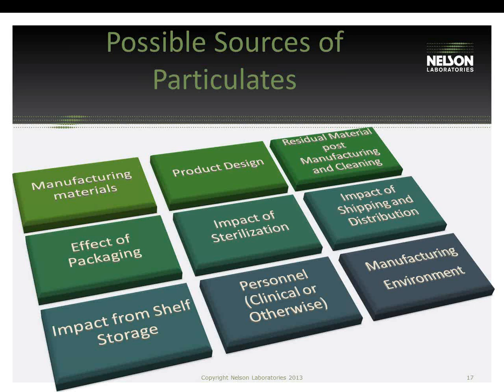Personnel, this is probably one of the largest ones, whether it be clinical or in a manufacturing environment or somewhere along the route from the manufacturing facility to the clinical facility. Personnel are probably the largest providers of particulate matter there is. We certainly find that true in our laboratory. Great measures have to be taken, and aseptic technique needs to be trained to provide sufficient protection from the particulates the personnel may provide and contribute to that product.